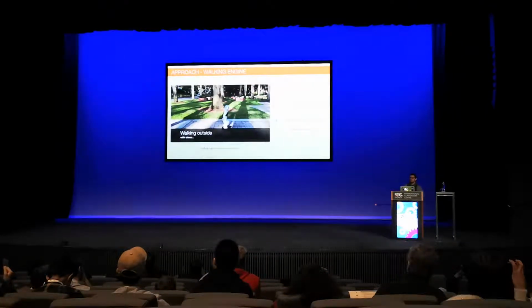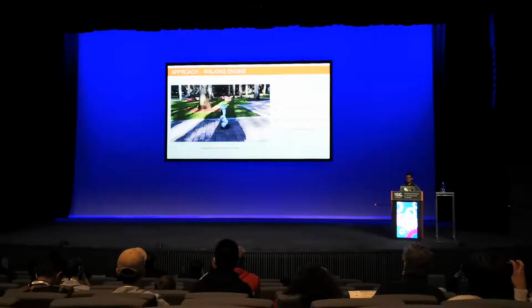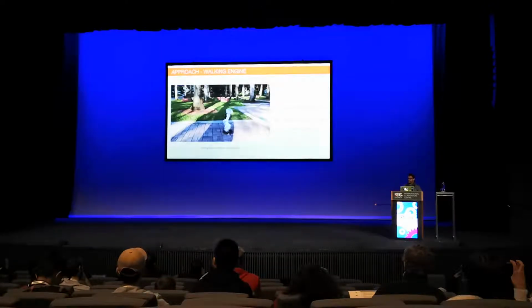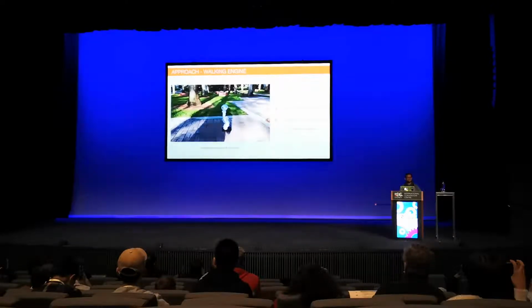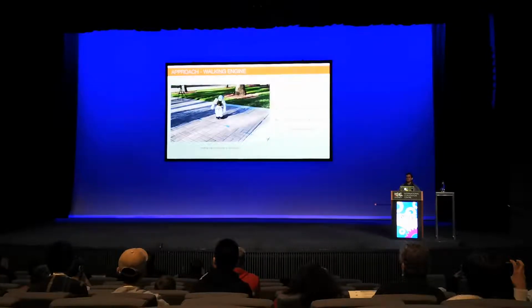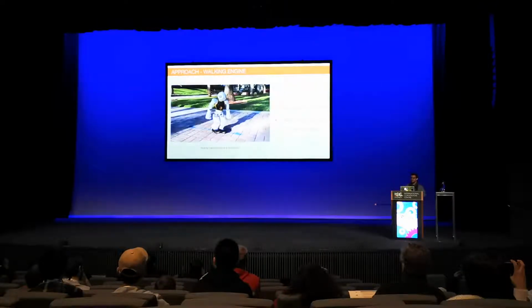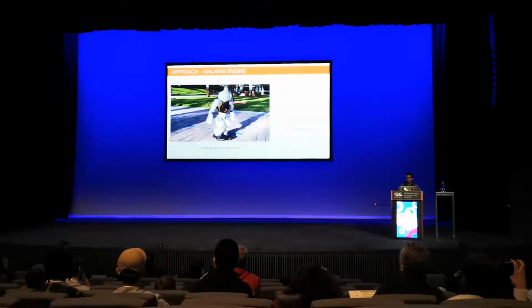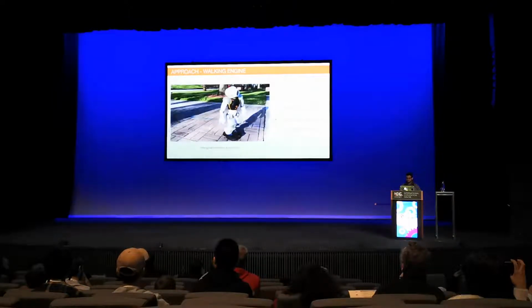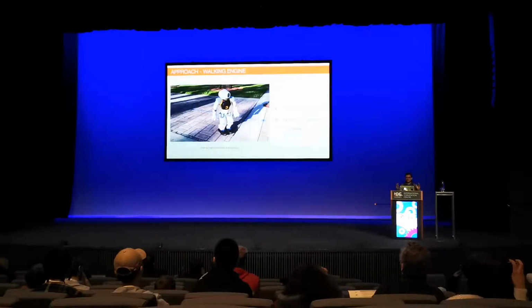The walking engine used for this research, proposed by Schuettert and Visser, is a closed feedback loop system that uses the equations on the slides to predict the trajectories of the center of mass and uses it to keep the center of mass from leaving this trajectory. The estimation of the center of mass is predicted by a particle filter, and it has a torso angle controller that maintains the robot in its reference trajectory. The step planner is also optimized using Newton's method to maintain the velocity of the robot throughout the reference trajectory, and all these ideas will become relevant for the walking controller proposed in this research.